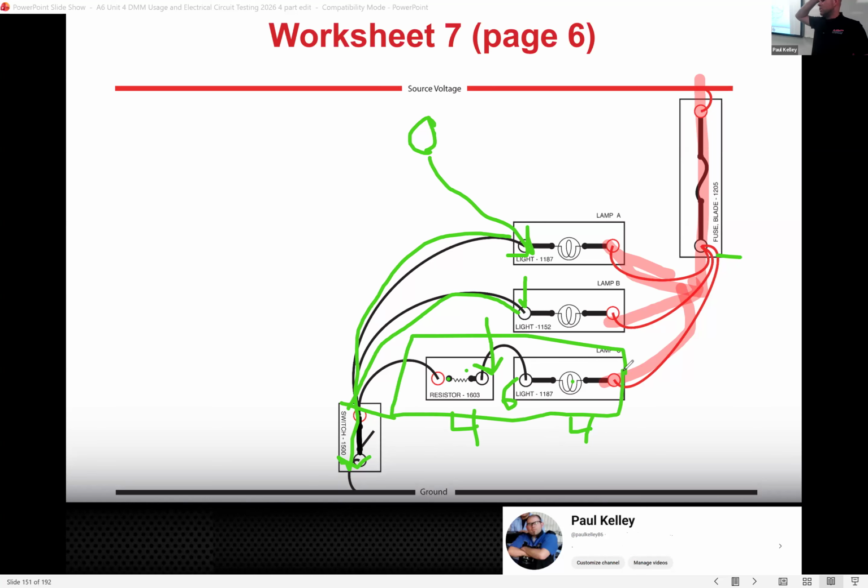You could have a bit of a series circuit inside of a parallel circuit, but that doesn't make it a series parallel, FYI. What I would like to point out why this is so valuable is, let's just say this resistor was more of like an unwanted corrosion. Remember how corrosion in the circuit becomes resistance? You'd have a bright bulb, 1, 2, 3.